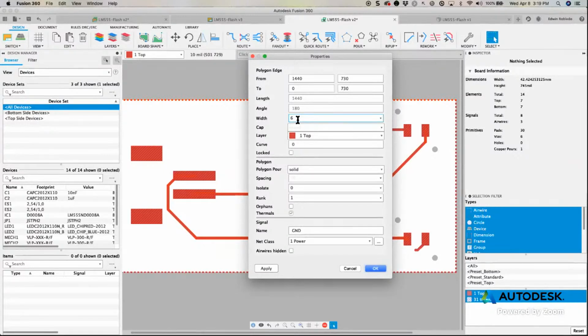I'll just make a side note here. Always use a value of 6 mils or greater. Some users, to have a better resolution, will set this really small, to like 0. In addition to the thermal connections being way too small to really work, it will create an immense amount of data when you generate your Gerber file. So you want to use values of 6 mils or greater. Yeah, basically two rules. Don't use 0 ever. And the second one is use the biggest width that gives you an acceptable resolution. You have that trade-off, but you can manage it.